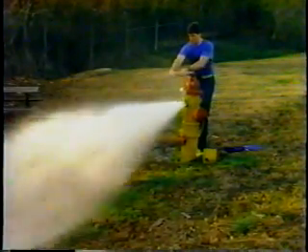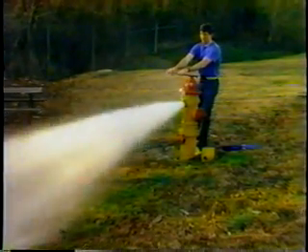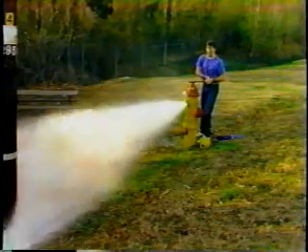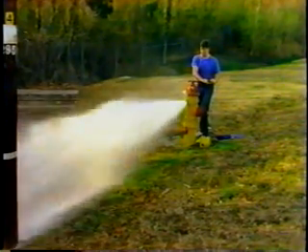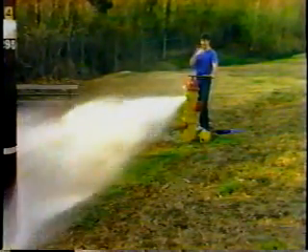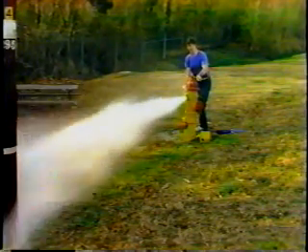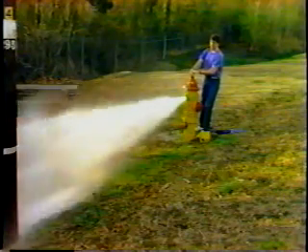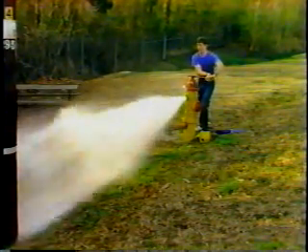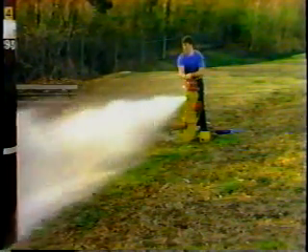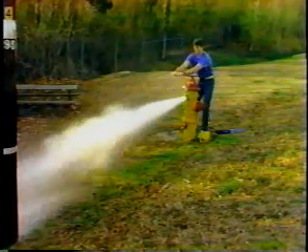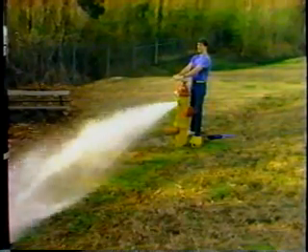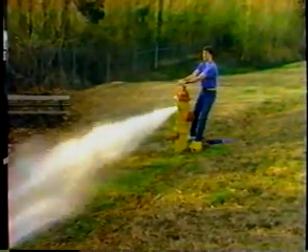Remember, when you're removing a cap gauge from a hydrant, that if the hydrant's still pressurized, that gauge can fly off and cause a lot of damage. So always look at the face of the gauge to make sure there's no pressure on the gauge when you're removing it. Also, a flowing hydrant can cause flooding damage. Please be considerate of your neighbors. And water hammer caused by quickly shutting off a hydrant can damage the distribution system. So the thing to remember when you're doing this type of work is be careful and be safe.